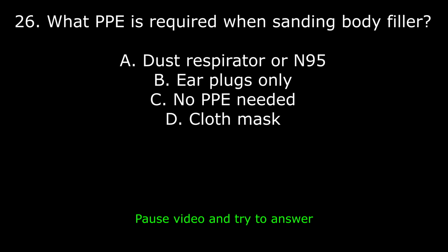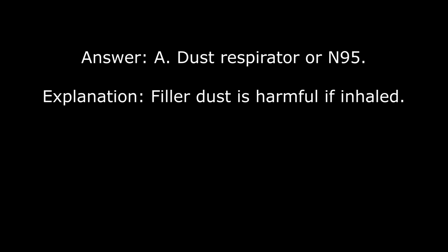26. What PPE is required when sanding body filler? A. Dust respirator or N95. B. Earplugs only. C. No PPE needed. D. Cloth mask. Answer: A. Dust respirator or N95. Explanation: filler dust is harmful if inhaled.